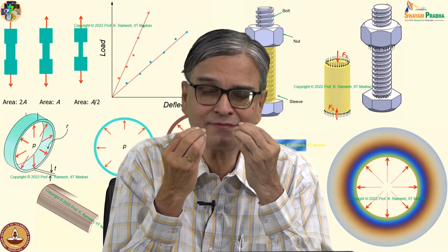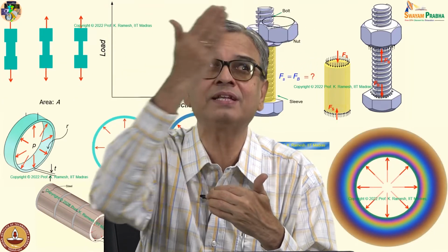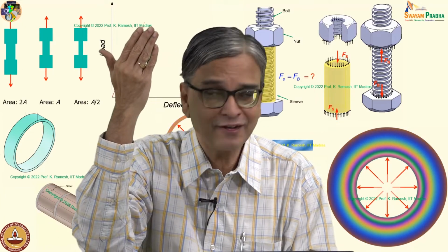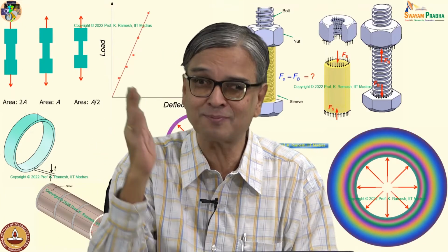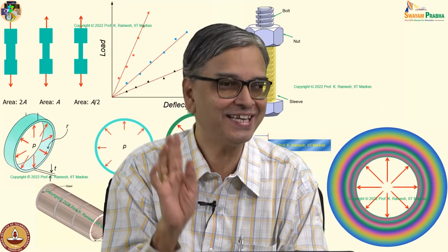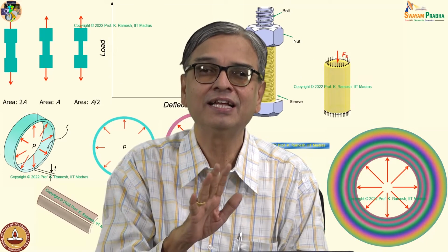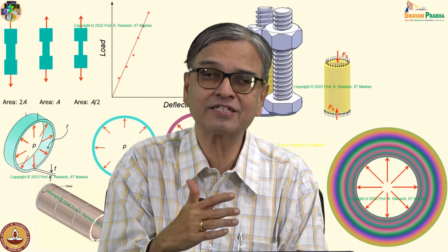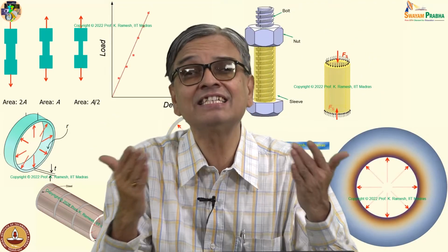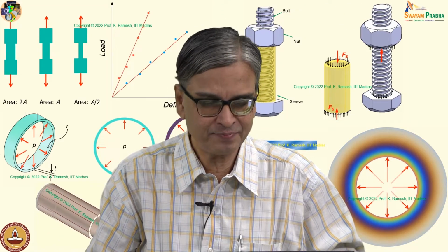If you perceive it with your naked eye, then it is large deformation, because if you look at a beam that is supporting this roof, it is deflecting. Fortunately, you and I do not observe it. If you observe, you will be the first one to get out of the room. Fine. So, you have to understand that we talk about small deformation, but for us to write the equations and develop our thought experiment, we exaggerate these. So, you have to keep that in mind.